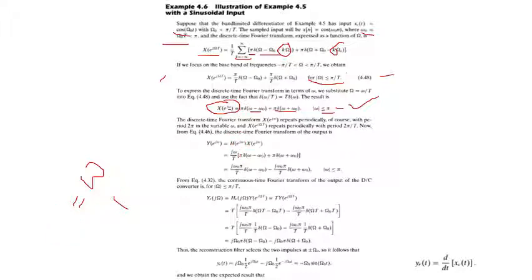So once you pass this input through this system, after some simplification, we get this. Now, this is still discrete, so we have to pass it through the reconstruction filter. Our output was Y(e^{jω}), so we first replace ω with capital Ω, because reconstruction is always in the continuous domain. And this is our reconstruction filter, and this is our final output.